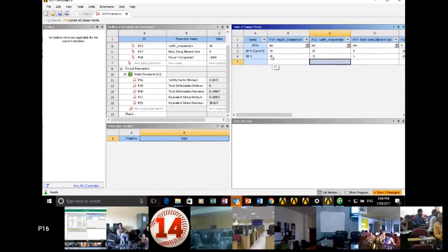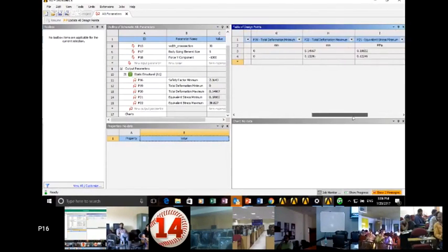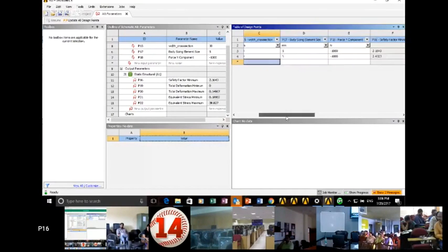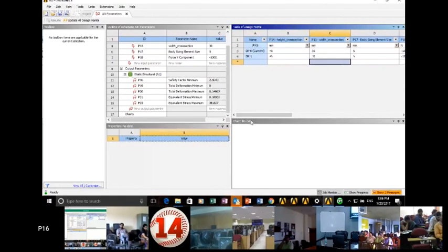When I have changed the height of my cross section from 40 to 45, the equivalent stresses and deformations have also changed. The deformation changed from 0.14 to 0.13. That is, there is a reduction in total deformation and also in equivalent stresses. This clearly indicates that by increasing the height of that cross section, keeping the width the same, the stresses and deformation in the body would be reduced. So this indeed clearly indicates that I am approaching optimality.